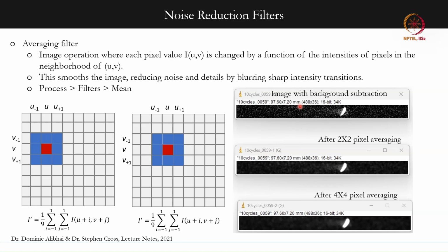If there are pixels with very high intensity that are disconnected from the flame boundary, the algorithm will map those points also as part of the flame boundary when they are ideally disconnected. So it is very important to remove these pixels where the intensity randomly shoots up.